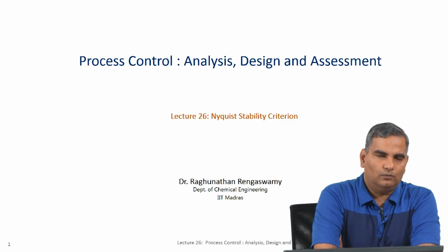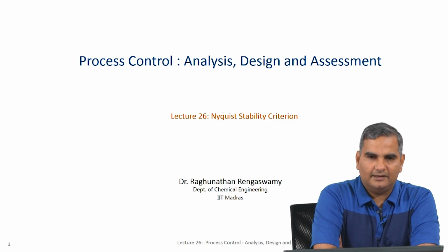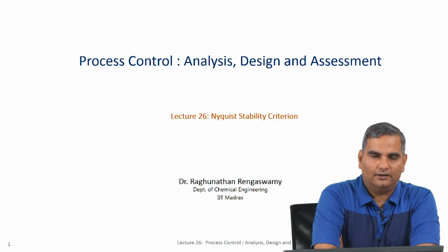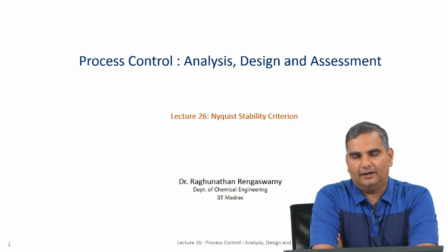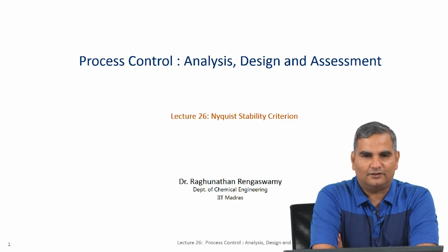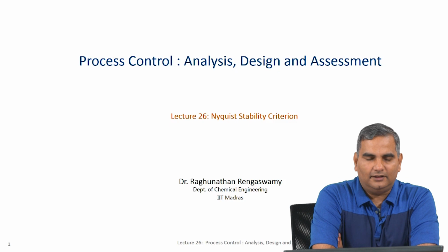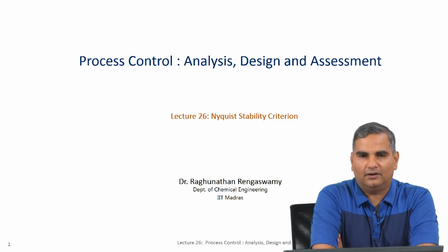So, I said what we do is we start on the imaginary axis at minus j infinity and then keep traversing the imaginary axis all the way up to j infinity, and then we take a long circular route covering all of RHP and then come back to minus j infinity. And this you can imagine just in your head that this is a clockwise movement in the S plane, and you might think about how am I going to compute all of this, right.